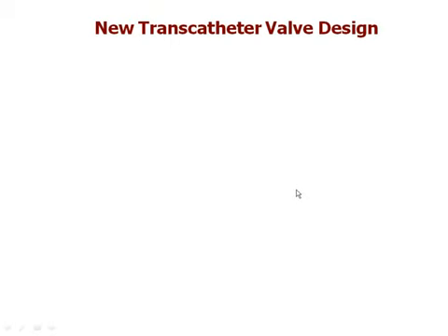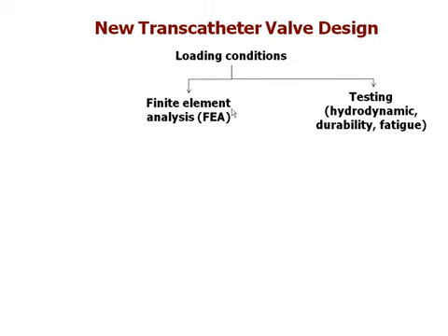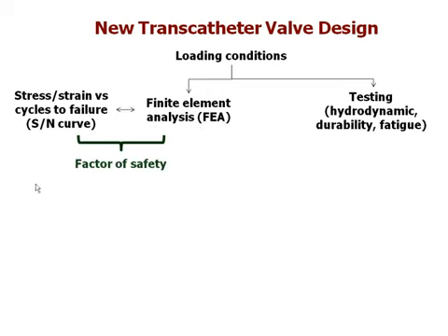And just to provide a framework on how new transcatheter valve designs may undergo testing, we have to understand the loading conditions of the different valves. Every valve design is going to have different loading conditions. The Heart Leaflet, the Edwards, the CoreValve, they're all going to interact with the aorta differently. So we have to understand the loading conditions. These loading conditions are then inputted in the finite element analysis and in the testers. And we already went over how we calculate the factor of safety.